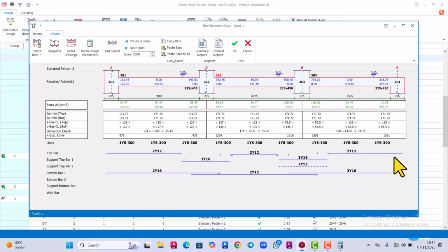Now, according to standards, Nigeria standard, I don't know, but for me, for a floor beam, that is a beam that is supporting a floor slab, the minimum size of reinforcement I use is 16 mm.